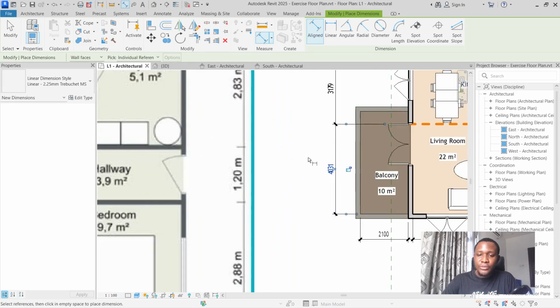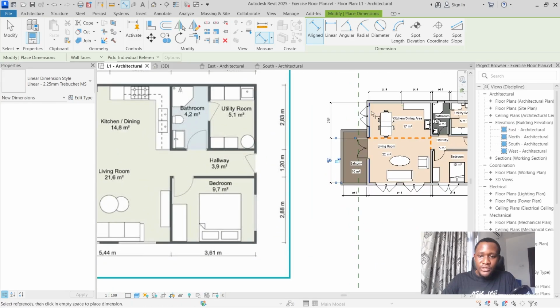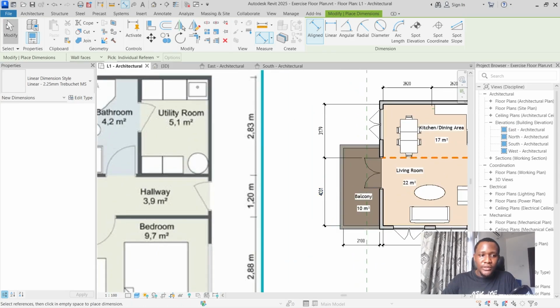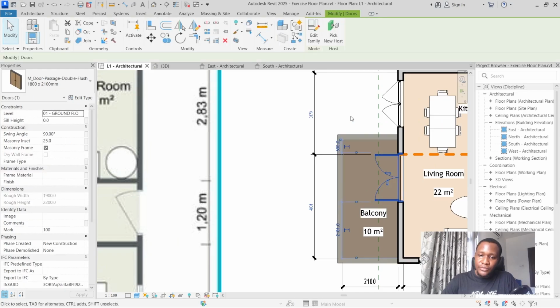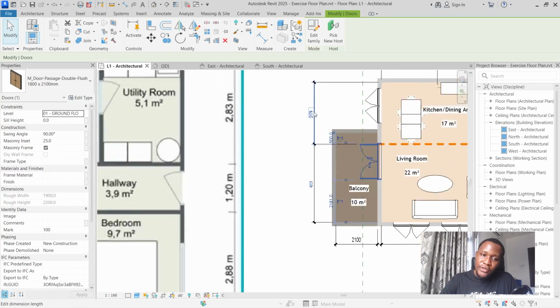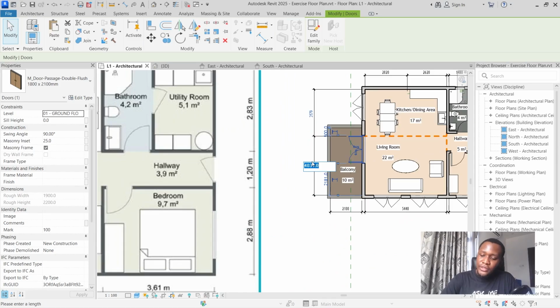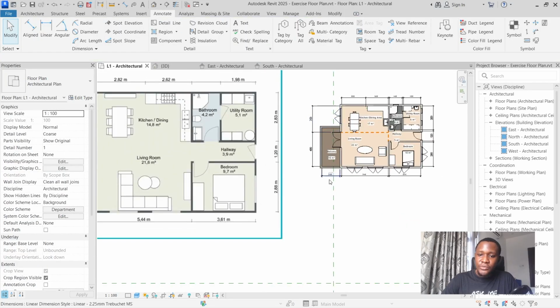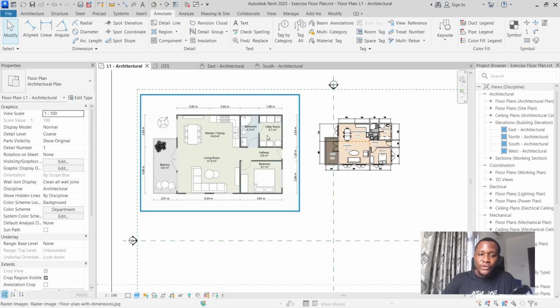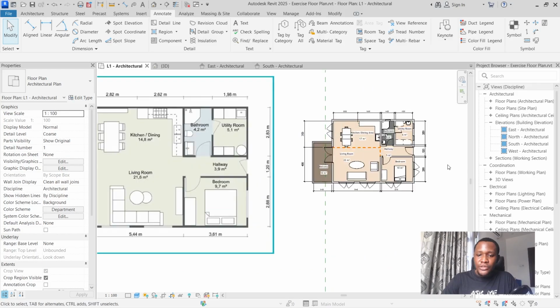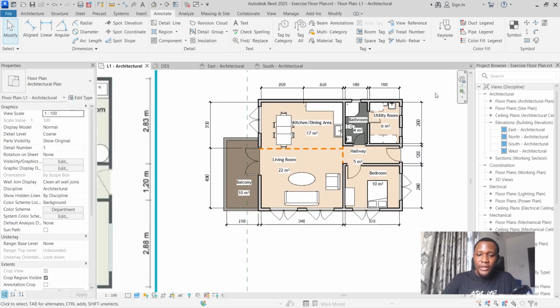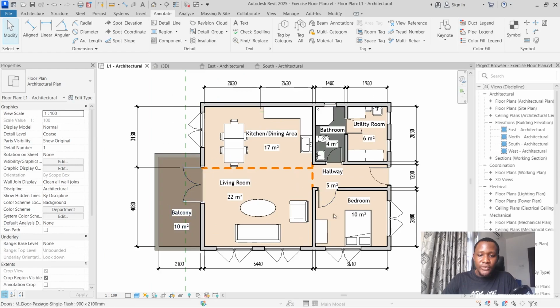The door we can actually move the door to get it to where it's supposed to be. So just go ahead and select this. And we're going to type 3.0, 2.83. Well, I'm going to use the reference of this one to 4.08, 4.080. So there goes our door, and we can leave the other dimension to be like that, because I noticed the building might become too small if we just obey what we see on that side. So that is how you can go about creating a floor plan in Revit and also annotate the floor plan the way it's supposed to be.